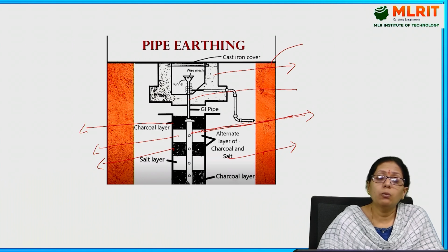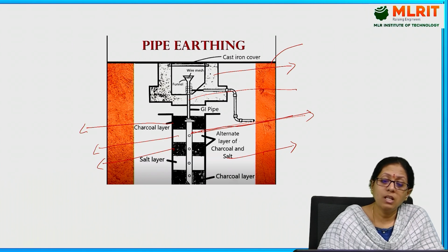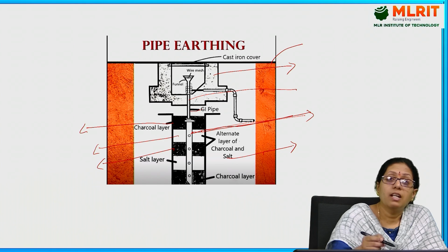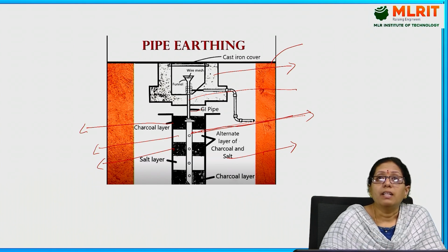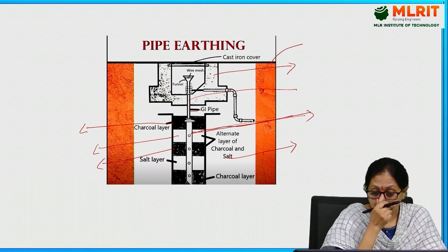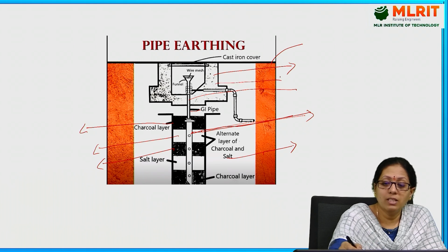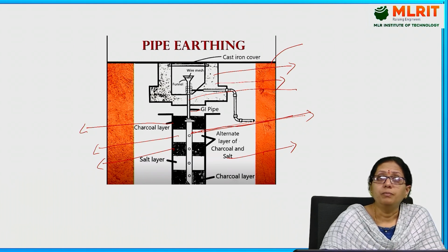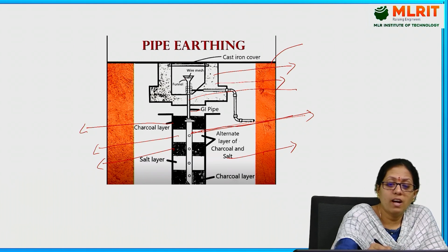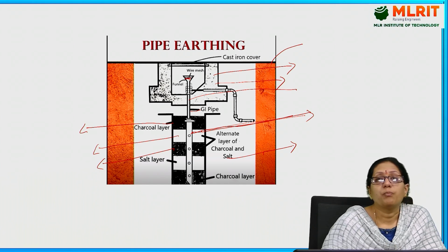After filling it with charcoal and salt material, we place the conductors, and these are again filled with sand, and a funnel is placed here.